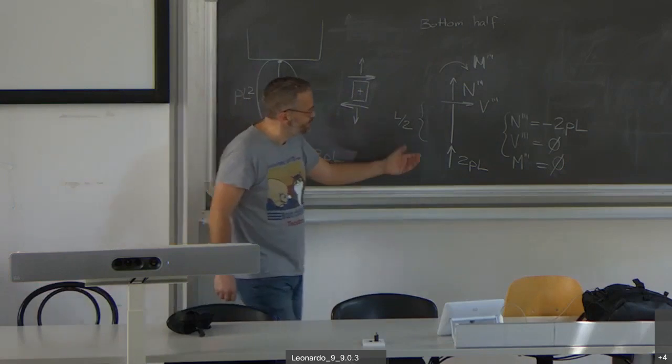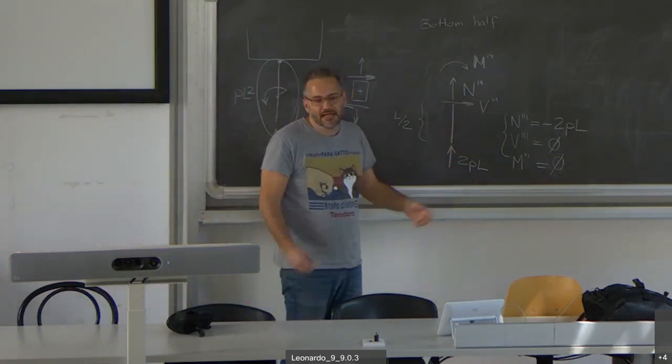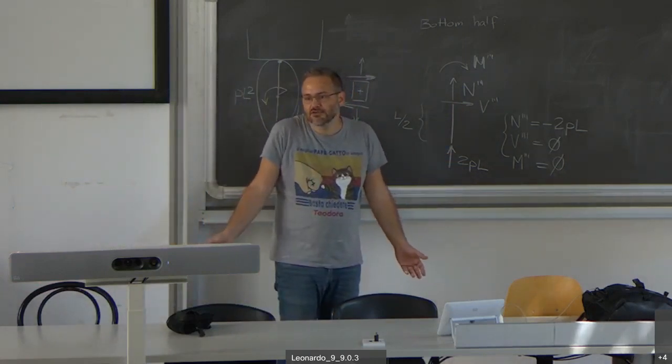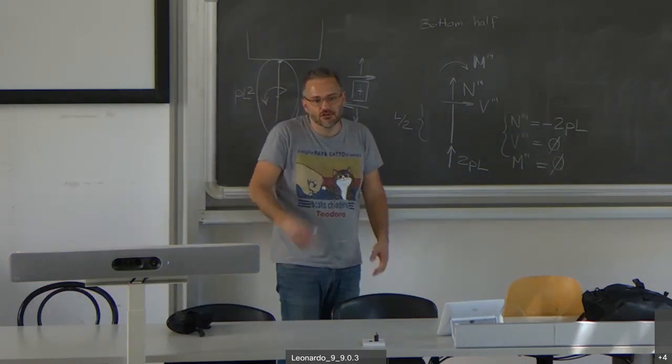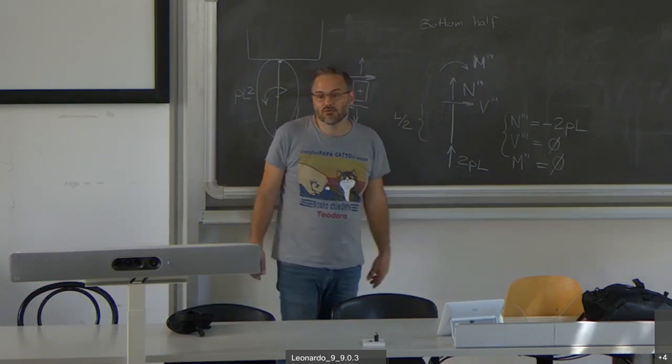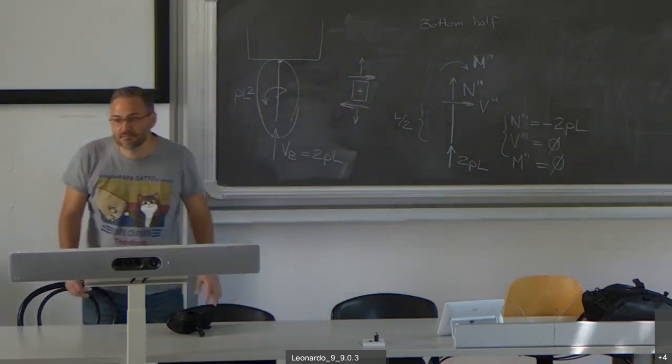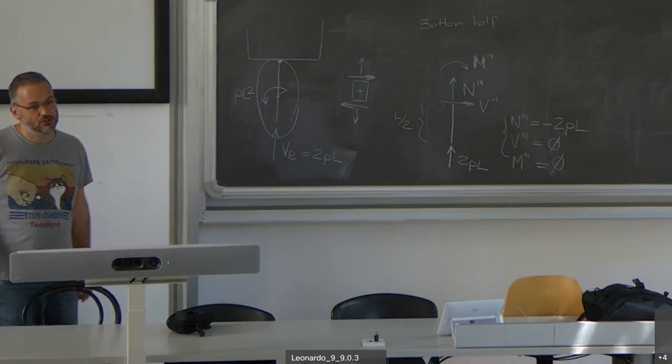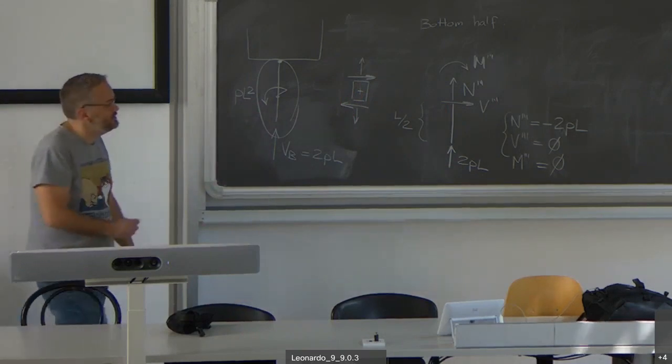Look at this. No other load applied than an axial force. What can the solution be? Axial force different from 0, shear and bending moment equal to 0. Exactly like what could happen in a truss member. In a truss member, that's the usual situation, just axial forces applied.